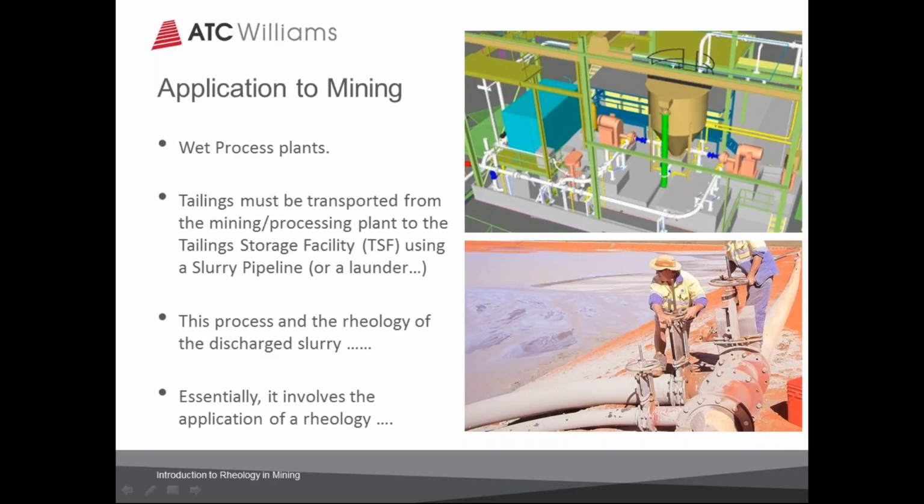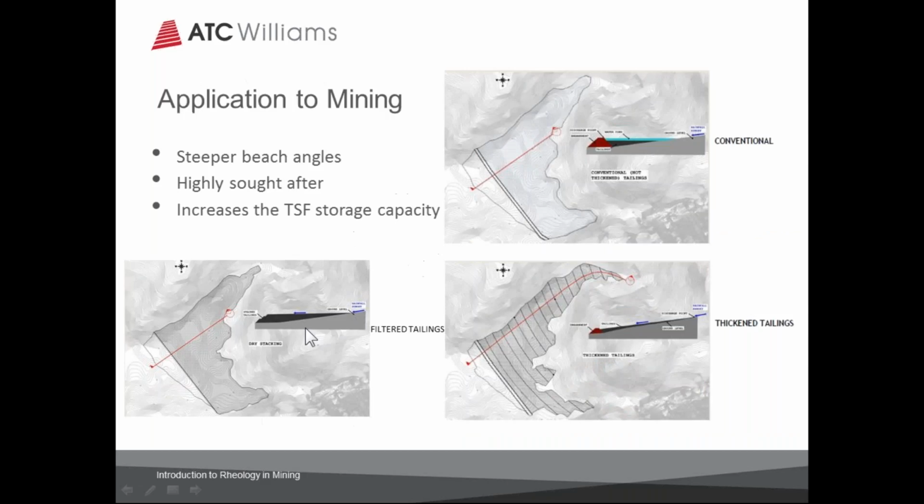That is usually done using a pipeline or launder, and this process is dominated by the rheology of the material because that is how it flows. We need to have a good understanding of the rheology in order to design, operate, and control the flow and disposal in the storage facility.